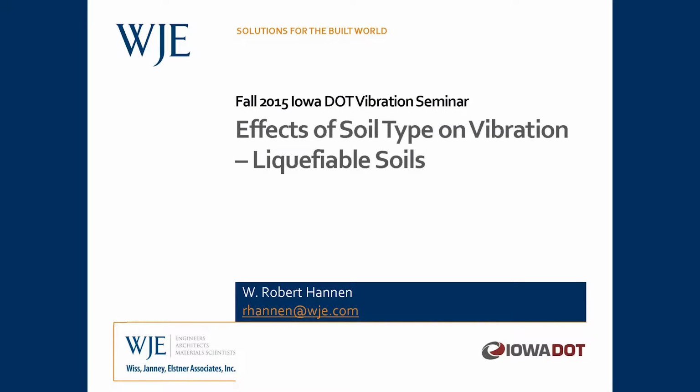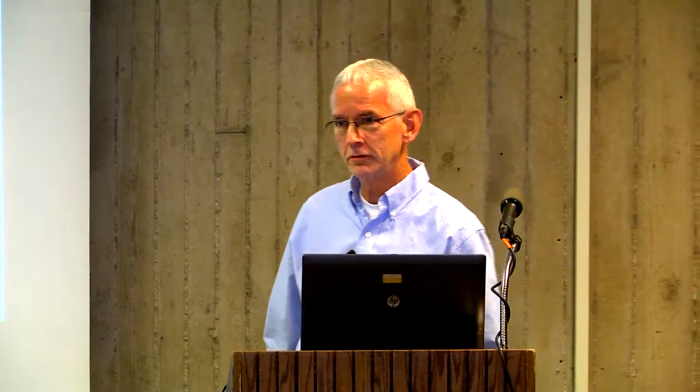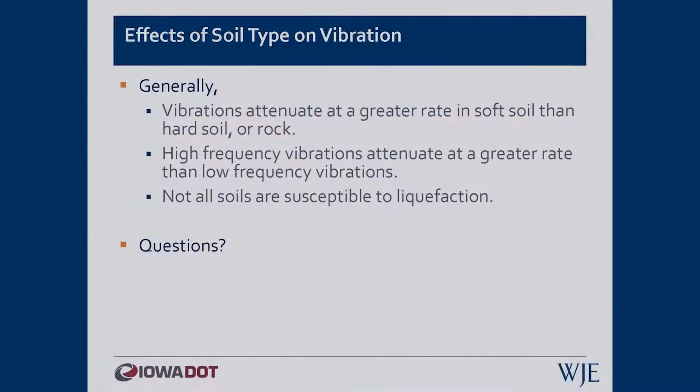My first talk is about the effects of soil type on vibrations. Generally, to give you a little bit of an overview of the results of what I'm going to talk about: vibrations attenuate at a greater rate in soft soils than hard soil or rock, high-frequency vibrations attenuate at a greater rate than low-frequency vibrations, and not all soils are susceptible to liquefaction.